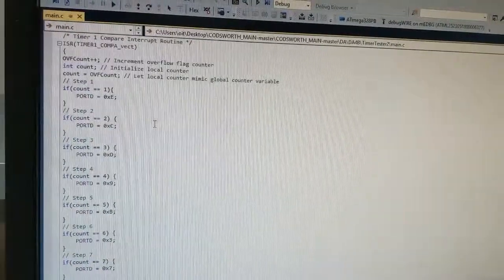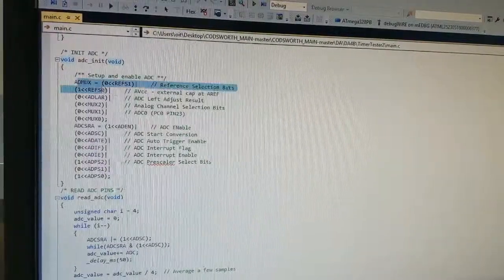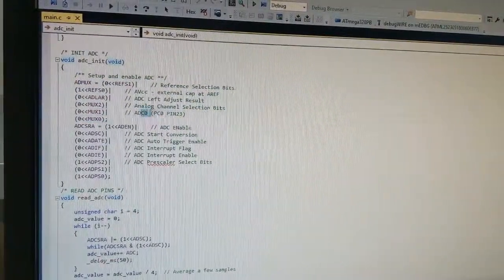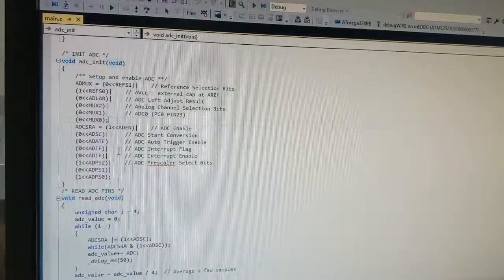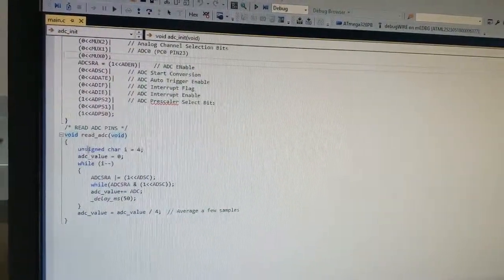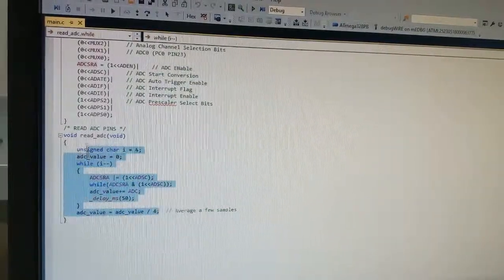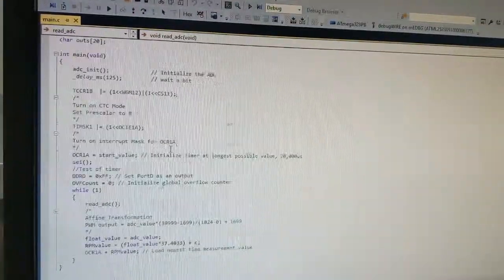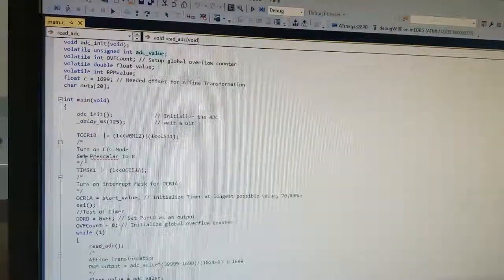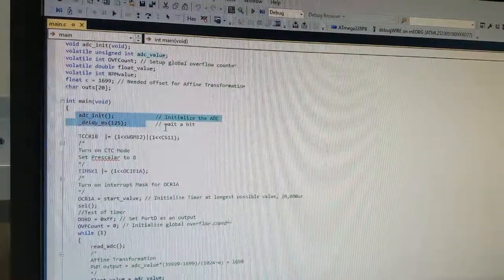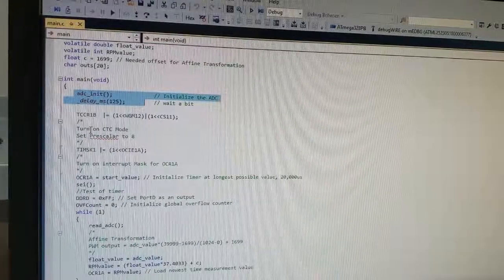Let's go back a second. This is set up to use the same process. So ADC pin 0 or PC0, and the typical setup here, and then it does our read value like this. It takes an average of 4 samples of that. The remainder of that, after the initialization, is some step time, to let it get rolling.